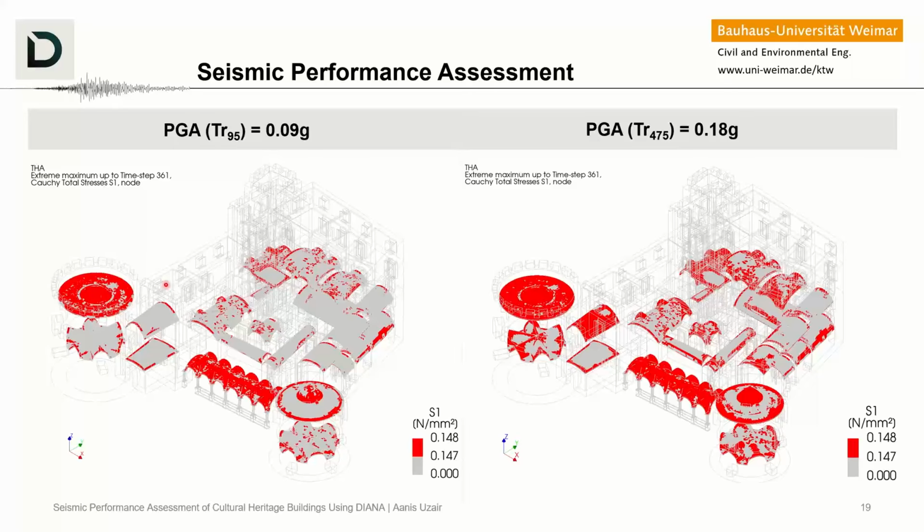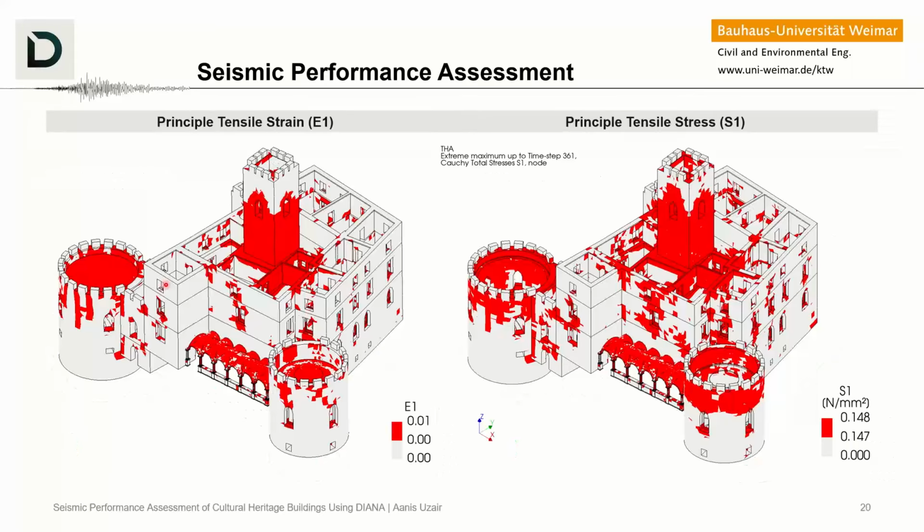For example, when the connections are known, then these are the parts which should be modeled with more clarity. Now, the stresses give you a good understanding of the concentration, but if you are interested, for example, in the orientation of the cracks, then maybe the strain is the correct information that you should be looking at. Between the stresses and the strains, you can see the strains provide a much better, clearer picture.